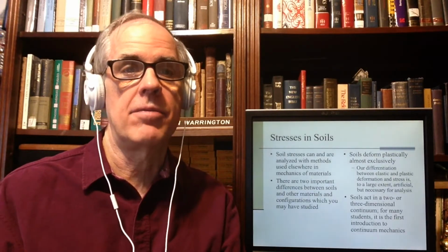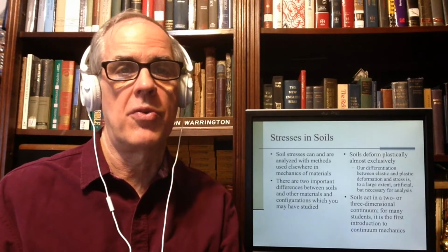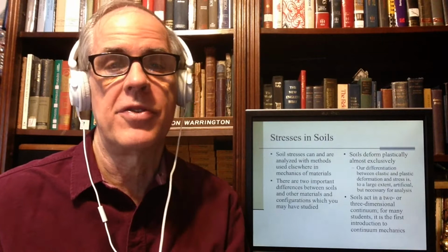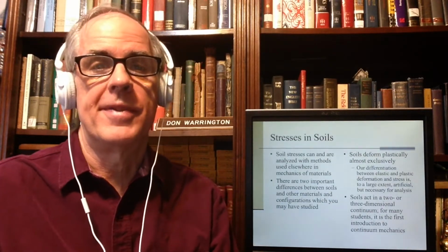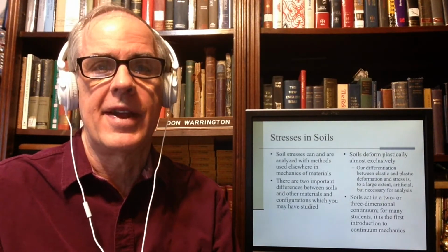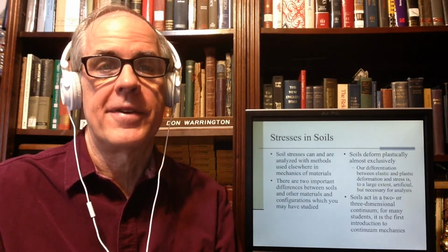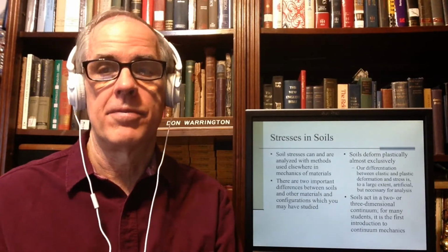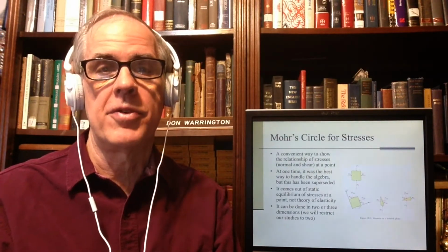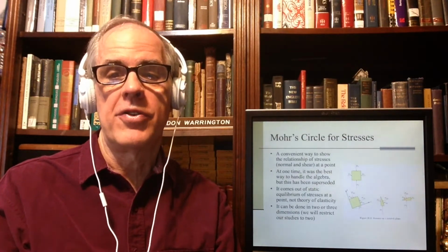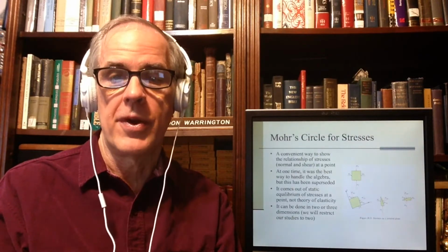Continuum mechanics can be, particularly with material that is as non-elastic as soils are, a little tricky. That's where the experience factor comes in with soil mechanics. But we have some tools at our disposal, and one of them is Mohr circle, which is something you should have been exposed to in mechanics of materials. It's a convenient way to show the relationship of stresses, normal and shear, at a point.